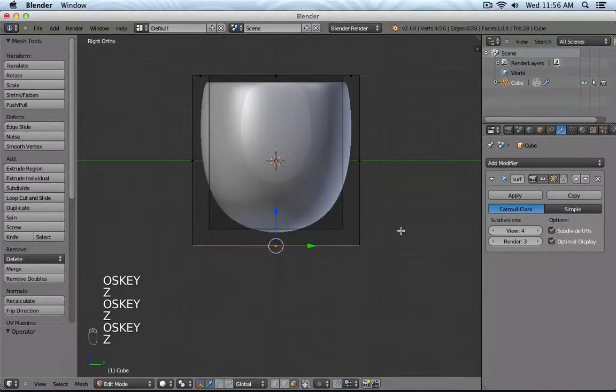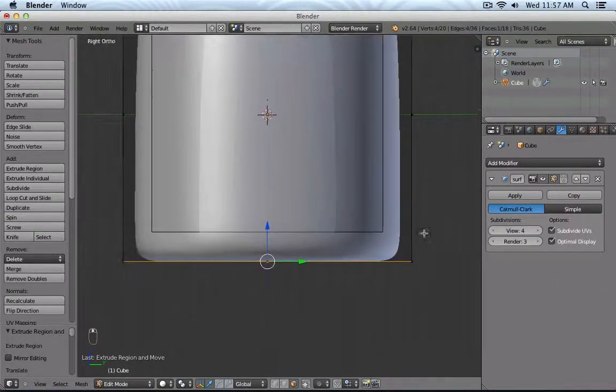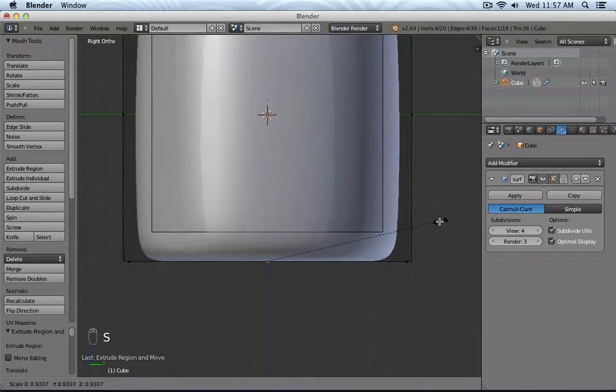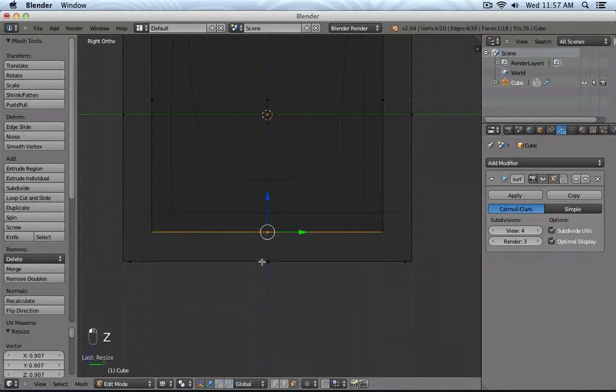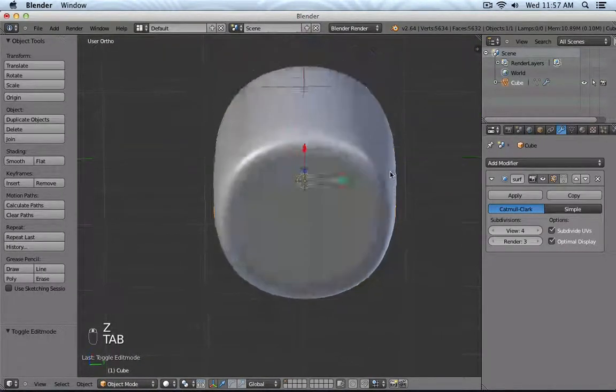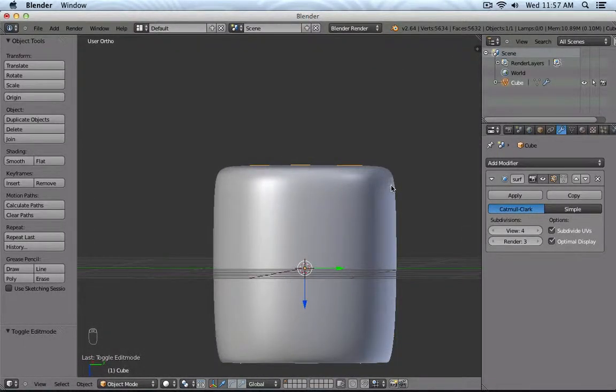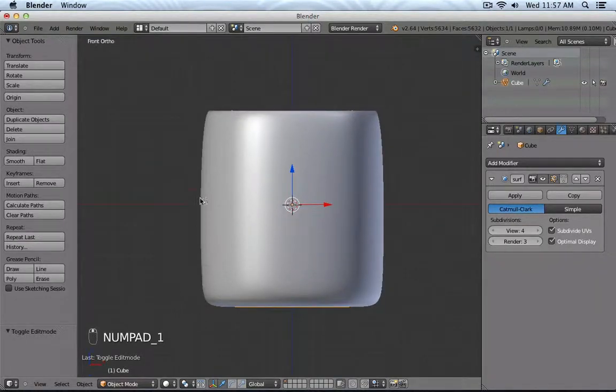So in my case, I'm going to undo everything because actually if I press E, I would like it to remain where that surface is created. And then I simply, after pressing escape, press S, and then, for example, scale it in a little bit. I can, for example, do the same here as well. Press E and then escape and S, move it in. So you can see that I have a nice, somewhat flat surface, nice rounded edges, and then it flows into the upper surface.